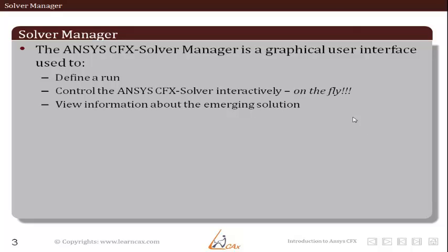Using CFX Solver, we can view the information about the emerging solution. Residual plots, monitor plots, solution convergence, all these can be checked while the run is in progress. We can export other solution data using CFX Solver. So the main purpose of CFX Solver is to calculate the CFD solution and export it for analyzing results to CFD Post.